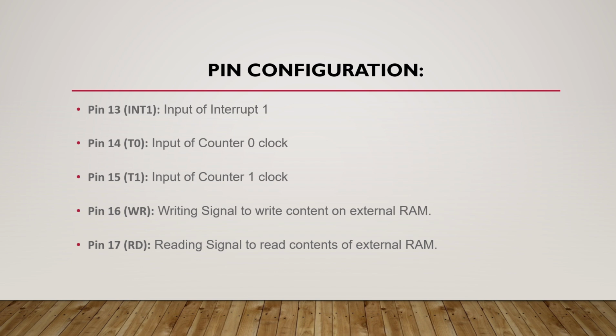Okay, pin 14 is the input of the counter. Here the counter means a clock signal. We can add some time to add delay to the process, and also we can speed up the present working scenario. We can also change the time signals. Okay, T0 and T1. Here the 16th pin is a writing signal to write content to external RAM.